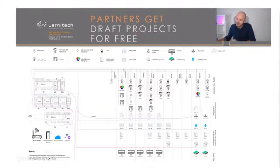So here, for example, the living room, what you have here is this light which is on-off, this light which is color, this curtain and this curtain, and also this sensor, this switch, and this sensor and this fan coil, and maybe some more. And you see where it goes and where it connects, and by its name you understand how many channels it uses, so how big a distribution board you need, and so on.